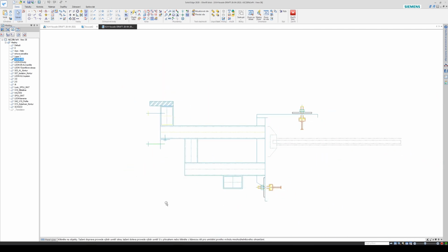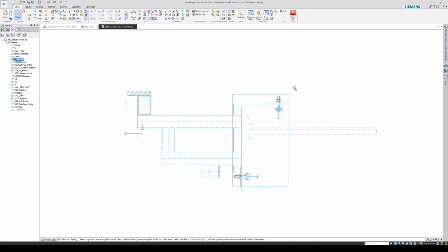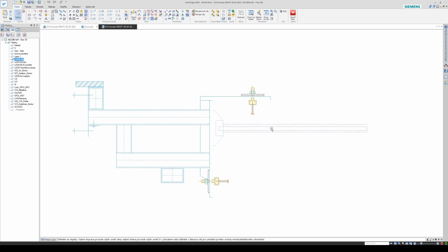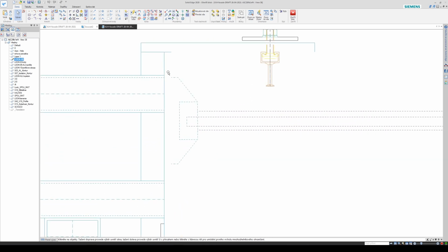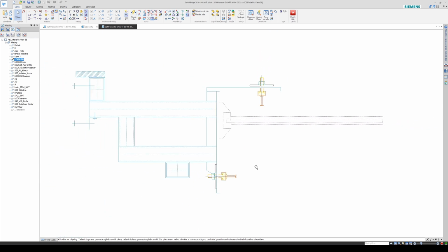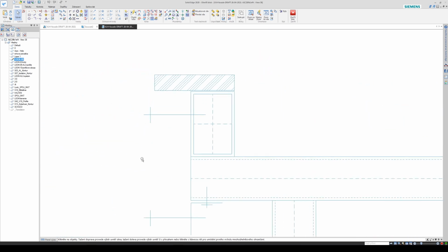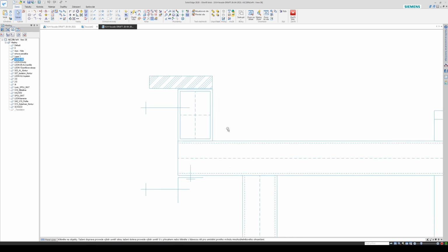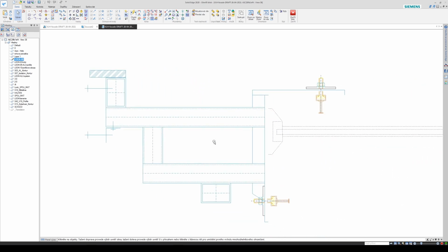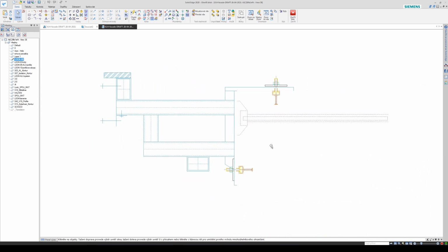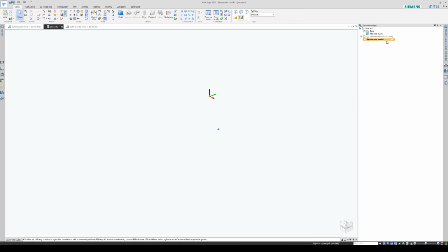Okay, I just selected all, then unselect the anchoring system, unselect this one here, and okay, I will keep this. Copy it, Ctrl C, then paste it in synchronous mode, and for example I'm locking the plane with F3, pasting it.